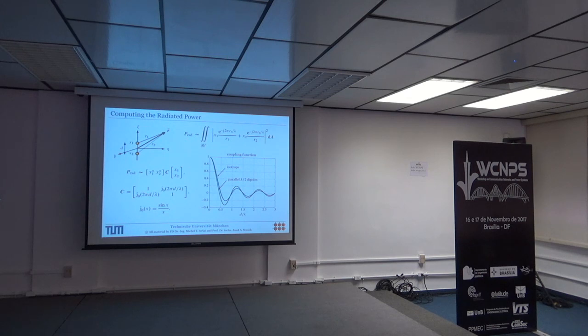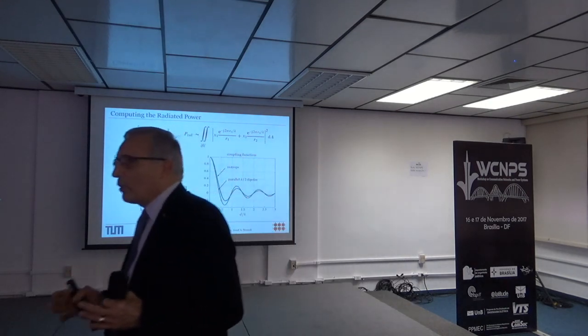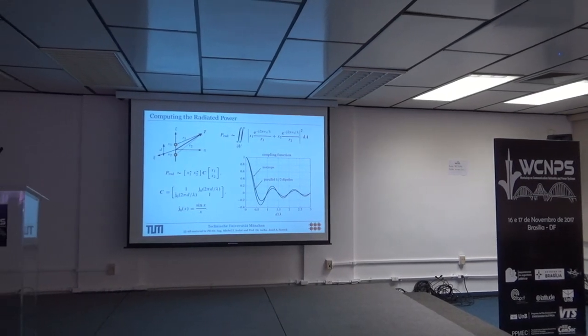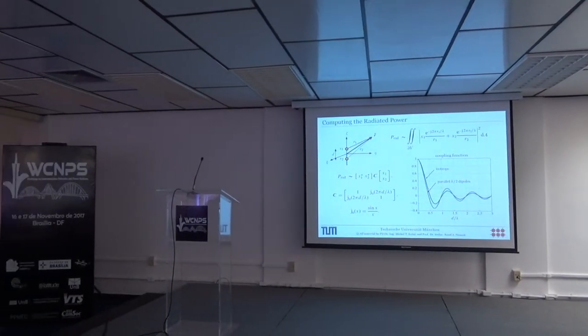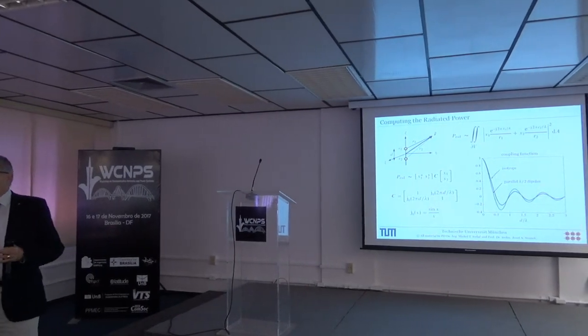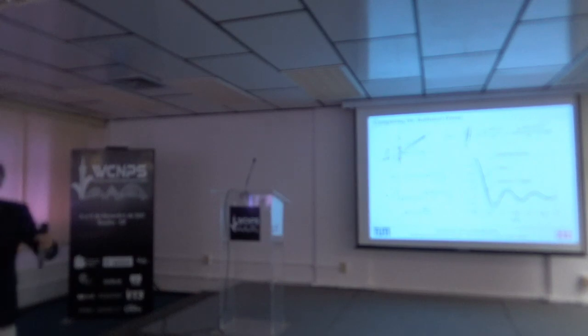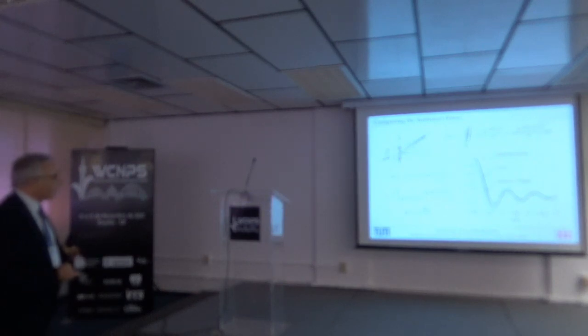This is important because many people use isotropes in their modeling, and anybody who knows about Maxwell theory knows there are no isotropic radiators. They don't exist. They are only hypothetical elements, but we can have things which are close, and for some analysis it's useful to work with them because it's much simpler than to go with the dipole elements, for instance. So this is one thing.